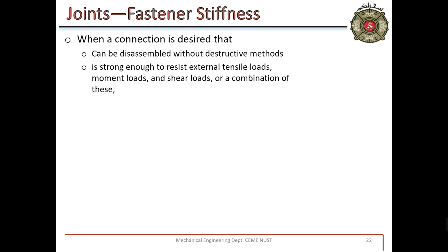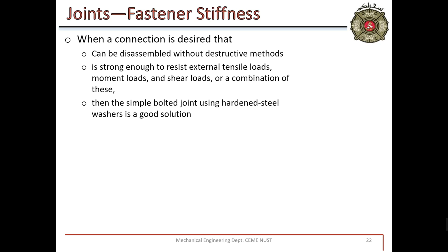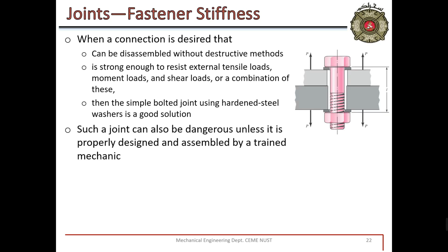Then the main topic was joint stiffness. Why do we need stiffness? As load is applied on bolts as well as members, some portion of the load will be borne by the bolt, and some of it will be borne by the members. We have no direct method to calculate F_B and F_member. So we use an indirect method if we know K_B and K_M.